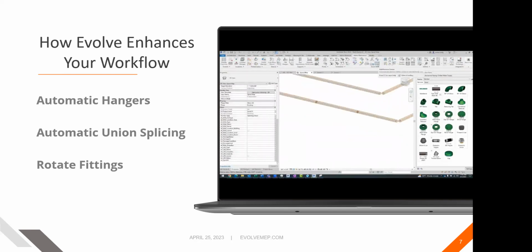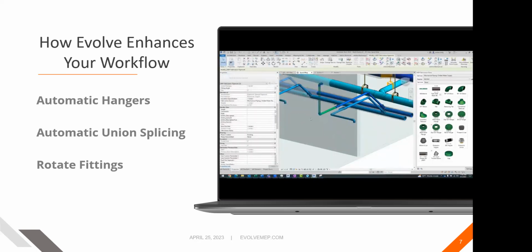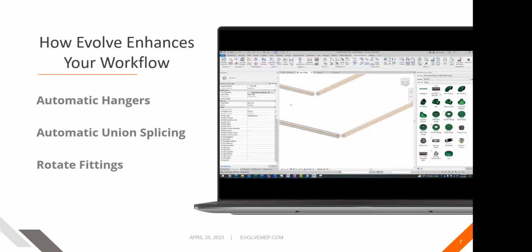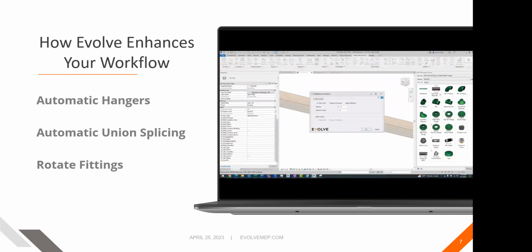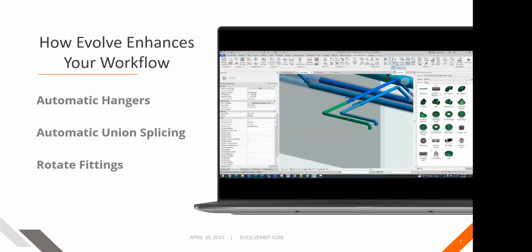With the optimized lengths that I was running, optimized length is determined by the actual size of that duct, right? Whereas this allows you to set your optimized length. So if you're running pipe and you have 35 feet of pipe and you buy 10 footers, or your 10 footers came in at 9.5, you can now optimize 9.5 for those lengths and know exactly how much you need.